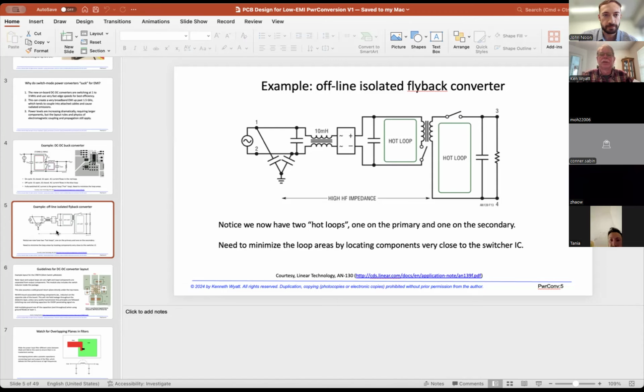That's one reason why I wanted to characterize all the samples I had received over the years, to figure out exactly what the absorbency was versus frequency. Most of the flexible absorbers become effective in the hundreds of megahertz and higher. In fact, most of them were designed for the gigahertz frequencies. They just happen to work okay in the upper hundreds of megahertz.